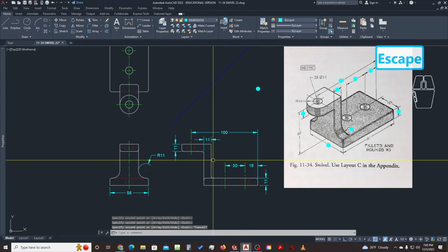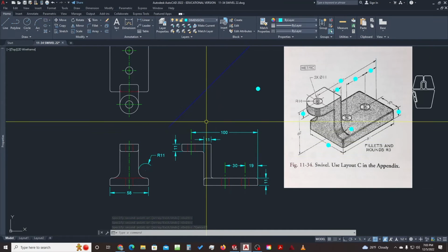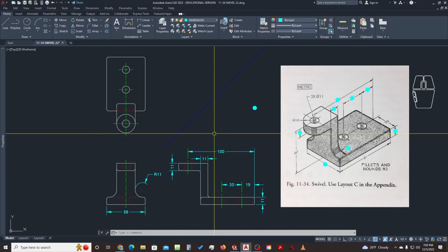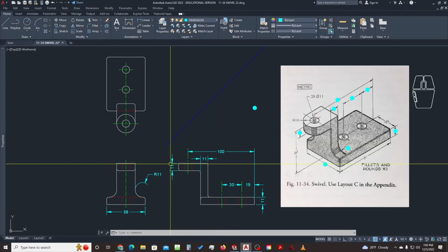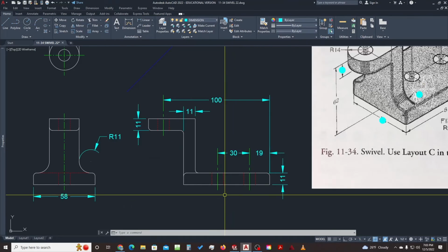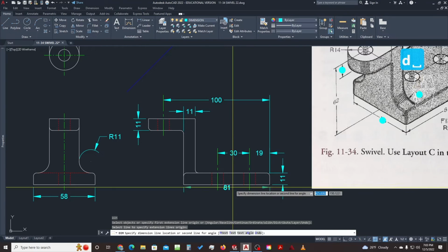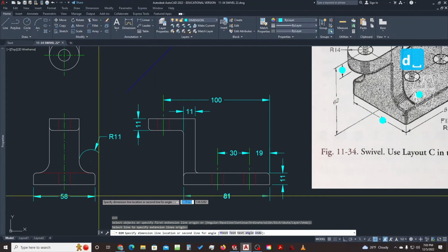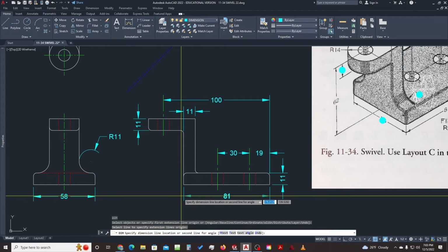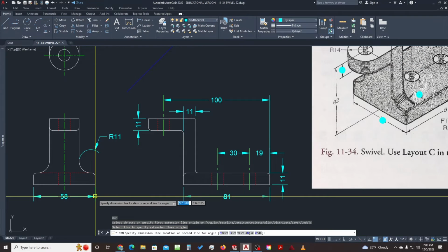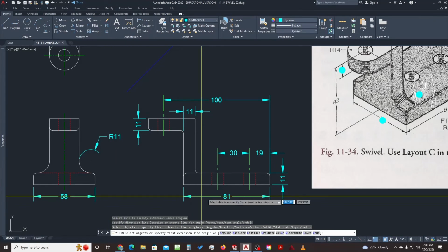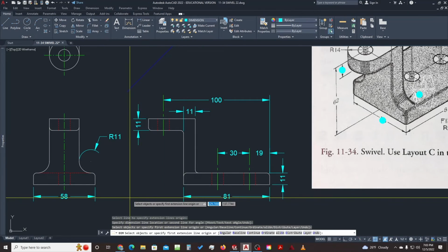And this view's already got a lot of dimensions. So I think I'm just gonna put the 62 in this view. But the 81 can go here. So 81 at the bottom. Use your cursor to kind of line these up. So, and actually I can even snap over here, but I do want this to come straight down and be in line. So it looks like my first row dimensions have the same distance.